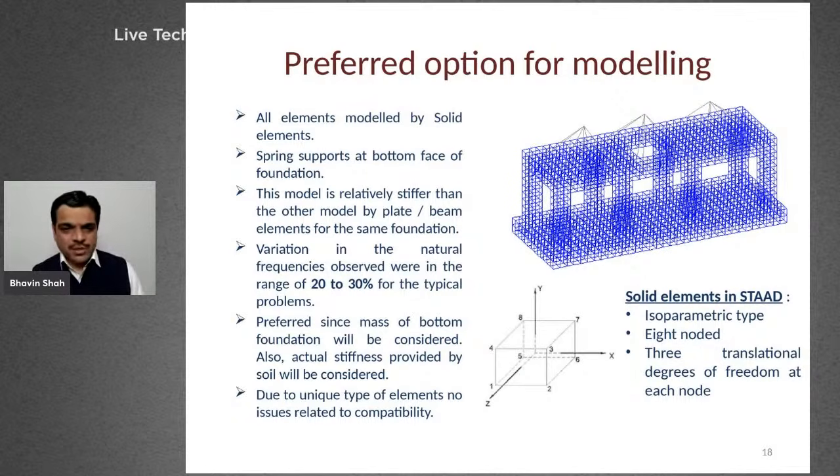And this option is preferred since mass of the bottom foundation will be also considered along with the mass of soil, and also actual stiffness provided by soil will be considered in this analysis. And as we just discussed in the previous slide, due to unique type of elements, there is no issue related to compatibility. Okay.